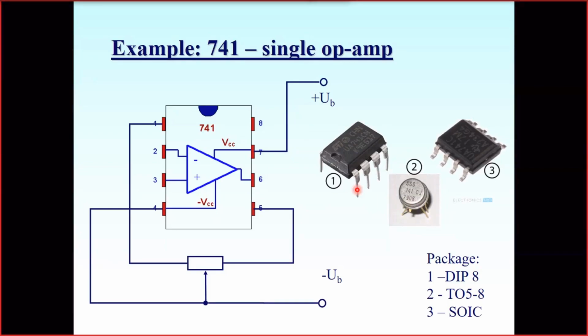Sorry, this is the standard pitch of the DIP package, and such a package is very well suited for prototyping using solderless boards, because it's much more convenient to solder such big chips. If you need something small, SOIC surface-mounted housings in a variety of types are available. We could get nearly every amplifier in a DIP package, and very often in a SOIC package too.